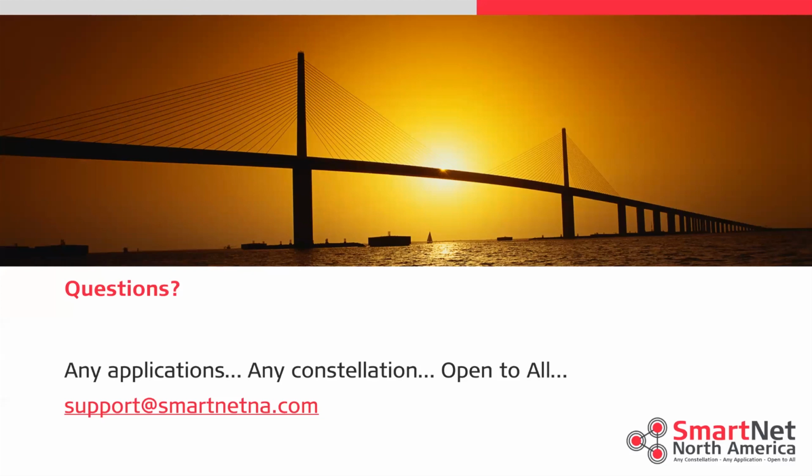If I want to stay on the coordinates that I'm on right now today, then yes, you would need to update your mount point so that you continue to receive the broadcast coordinates in the previous reference frame, basically today's reference frame and realization. Hopefully that answered your question.